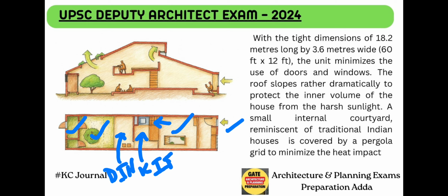So basically, whatever the climatology they are saying here, towards the courtyard, he has used the principle of traditional Indian methodology, or courtyard houses. In normal traditional Indian houses we have a courtyard, so he has used the same concept. You can clearly see in the section. In this section also, see what is happening: the hot air is becoming lighter and rising up and escaping through the louvers of this courtyard. Okay, so hot air rises, and this is the courtyard, guys.